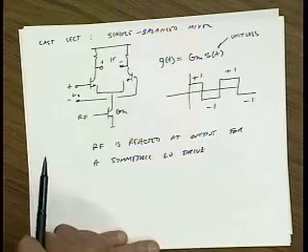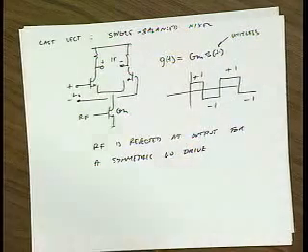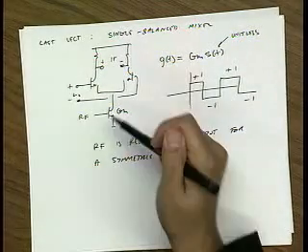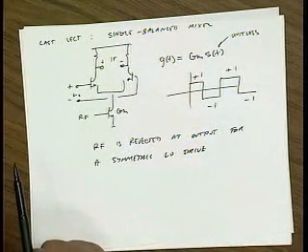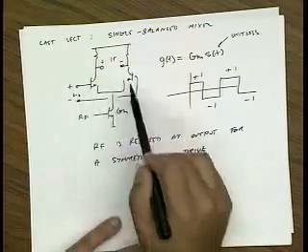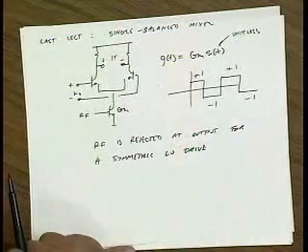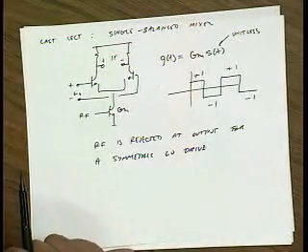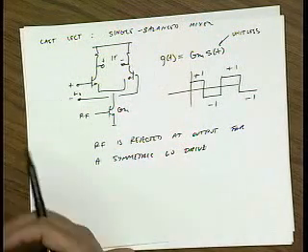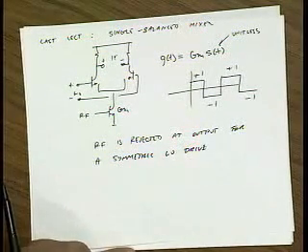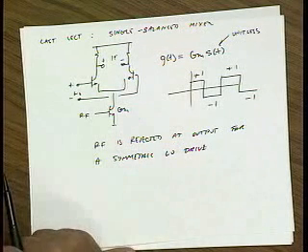Okay? Let me also just kind of intuitively tell you guys something about the noise of this circuit. This is another discussion that came up in office hours today. Last time we talked about the noise in mixers in general, and we noted that one thing that makes the noise of mixers high is basically the noise at all the image frequencies folds into your IF band, and so you get a lot more noise than you would from a time invariant circuit.